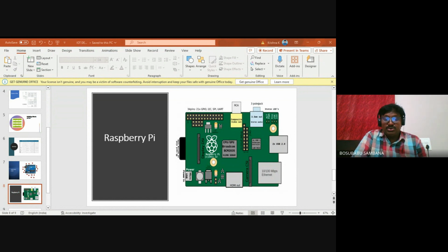The Pi 3 Model B Plus and 2 have 256 MB to 1 GB of RAM, while the Pi 4 has up to 8 GB of memory, and the operating system is stored on secure digital cards, especially micro SDHC cards. The models carry between 1 and 5 USB ports. A standard 3.5 mm tip ring sleeve jack is provided for audio output, and both HDMI and composite video are supported for video output. Several general purpose input output pins provide low level output and are compatible with standard protocols like I2C,